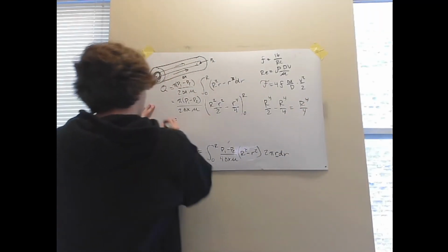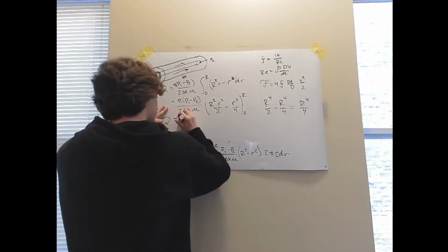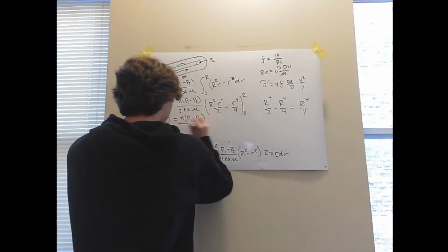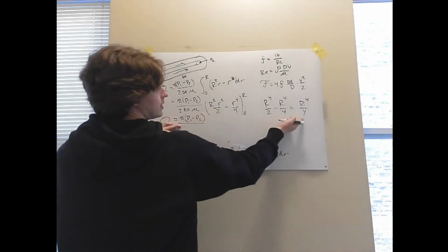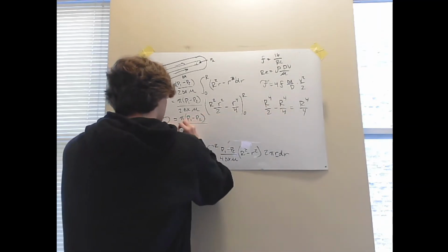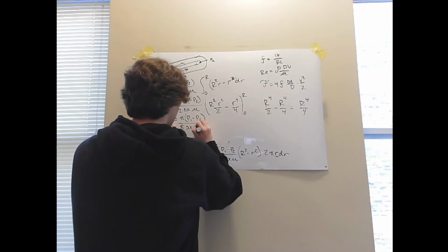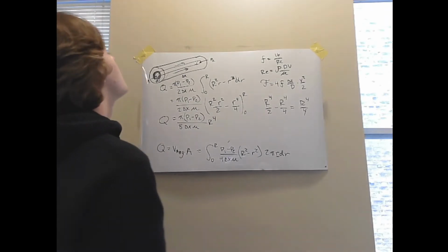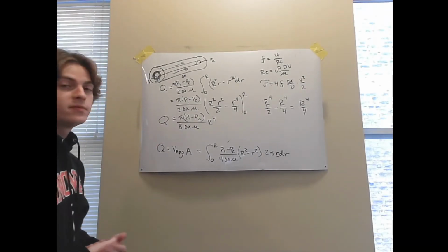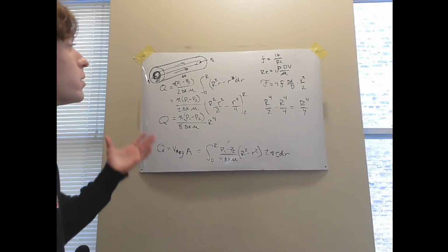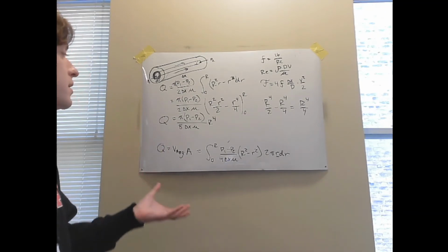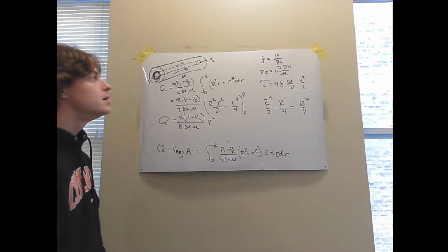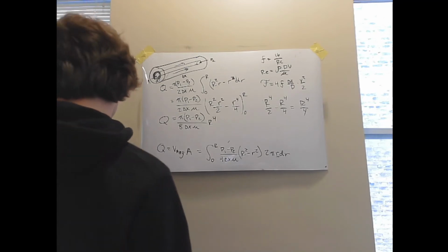So for our volumetric flow rate, we have pi times P1 minus P2 over 2 times the 4, which is 8 in the denominator, times delta x times mu, times r to the 4th. And so now we have our volumetric flow equation. So from here, what we need to do is get it in terms of the diameter, and then we can apply Bernoulli's equation and show that the fanning friction factor is always 16 over the Reynolds number.